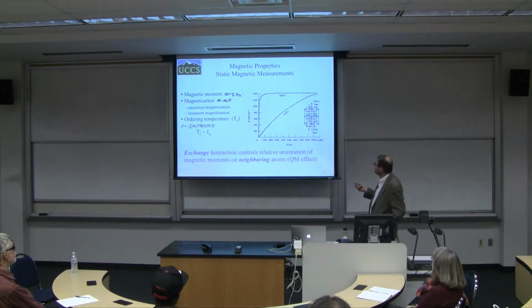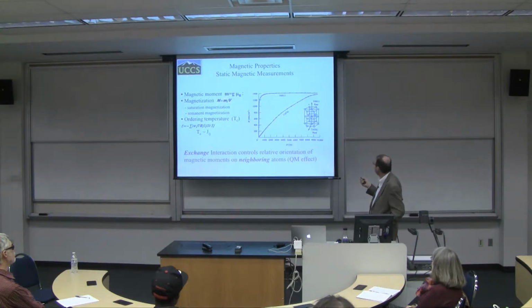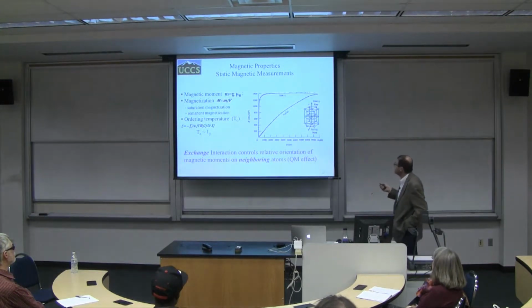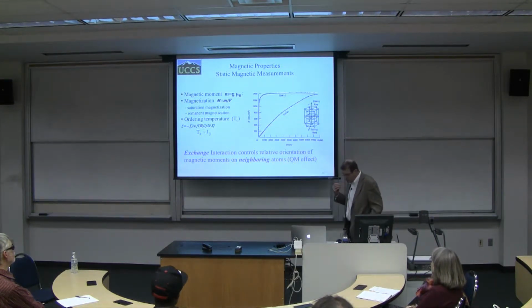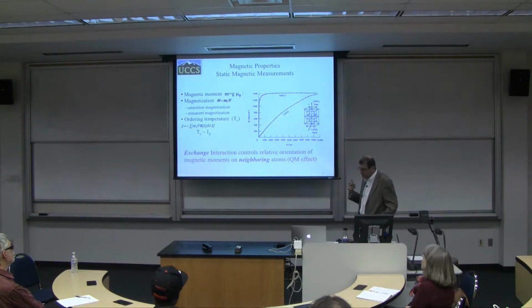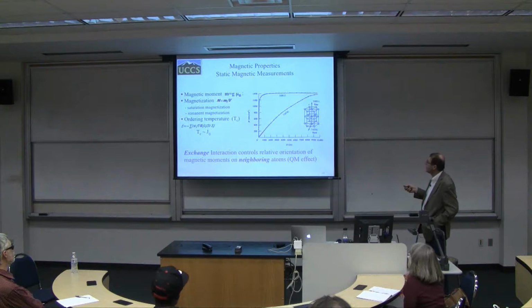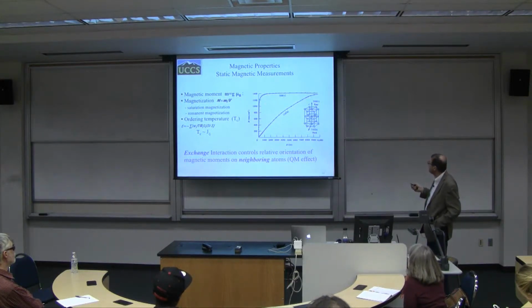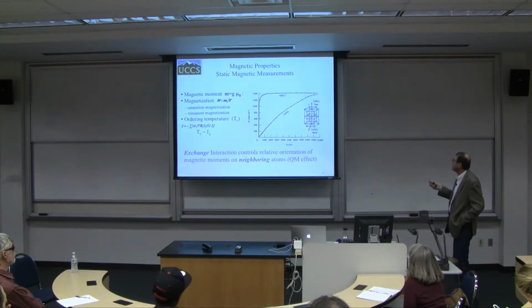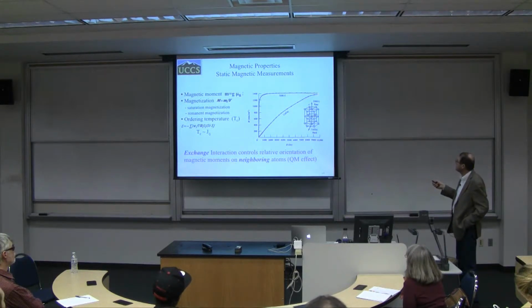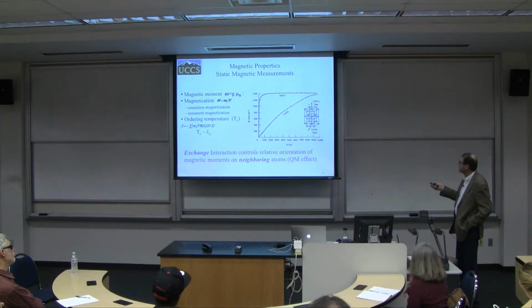Magnetization is basically the ratio between the moments I have within the volume of my unit cell divided by the volume. There are two important parameters which determine the behavior of a magnetic material. One of them is the maximum value of M, the so-called saturation magnetization. When I apply a very strong magnetic field for this hexagonal structure, I am going to reach a certain maximum value of saturation magnetization.